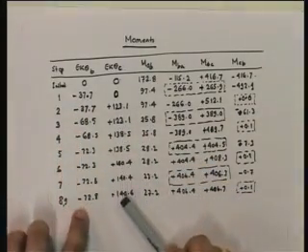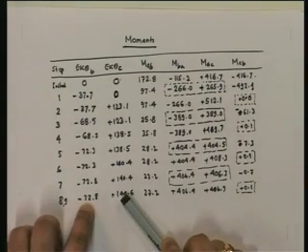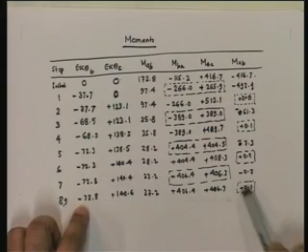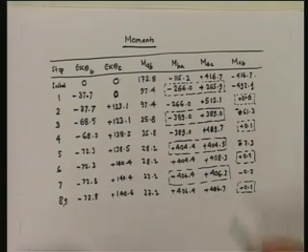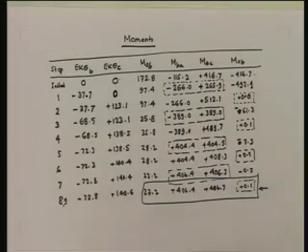Keep doing that till you have a situation where even when you release, you essentially get the same thing, which basically means that you have balanced forces here and you have balance here. So therefore, these are no longer clamped because you have released, and this is the final member end bending moments. So these are the final member end bending moments, and in essence, what are you doing? You are distributing moments. So this in essence is the background behind the moment distribution method.